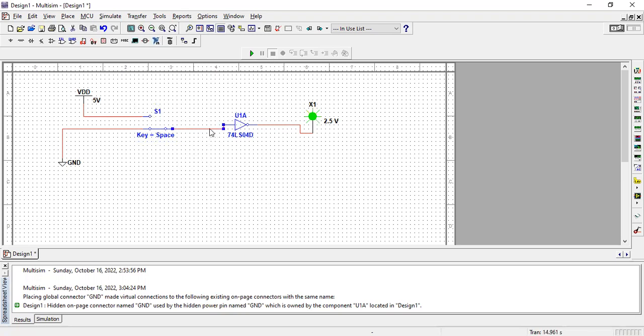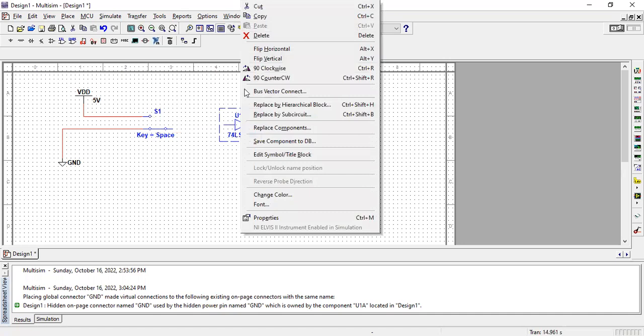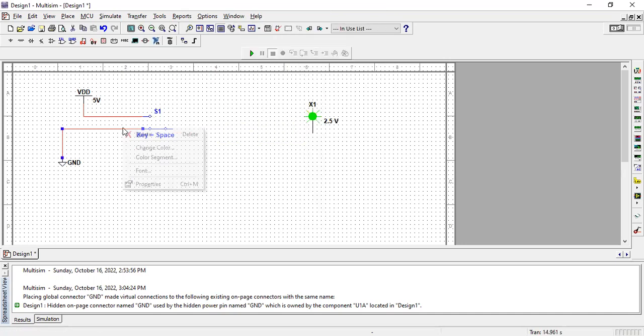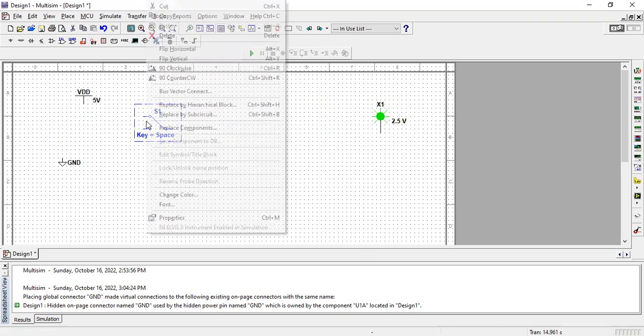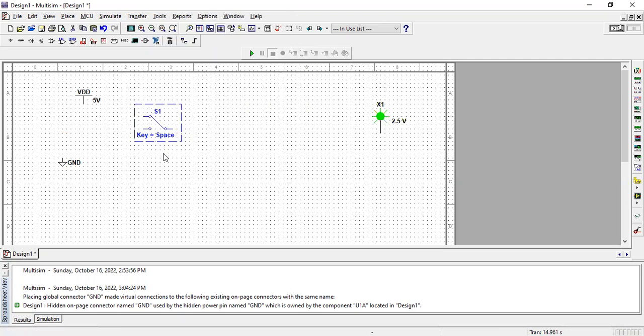So first of all, I'm just going to modify this circuit. We need some basic components as it is formed. Therefore, I'm just going to eliminate this logical circuit. And we know that in the case of the AND gate, we have two or more than two inputs. So therefore, we need two switches. In the same way, we need one LED in order to get our output. So I'm just going to copy this switch as it is formed, so that I can apply 2 or 3 inputs over here.